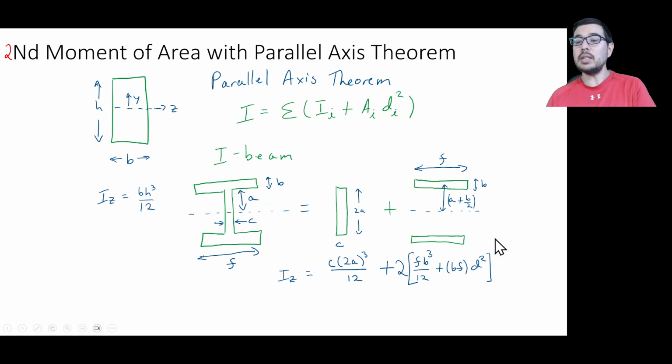But using the parallel axis theorem, what do we get? Well, one, we're going to double whatever we get for the top, because this is going to be contributing the same amount at the bottom. And then using the parallel axis theorem on this portion, what we have is the second moment of area for this horizontal slender rectangle, and that's going to be the width times the thickness cubed over 12, and then we have it offset a distance given by d squared.